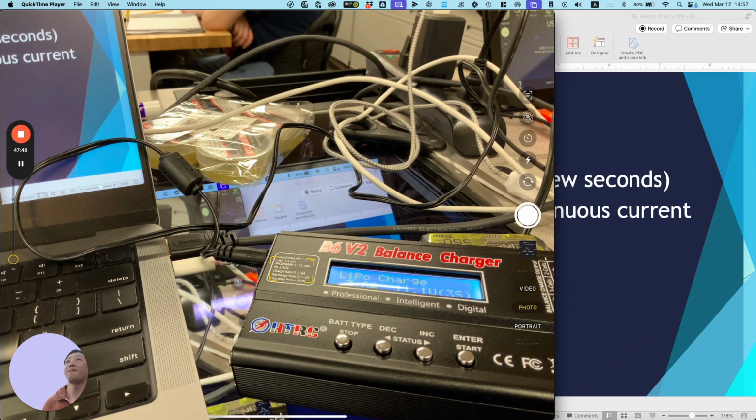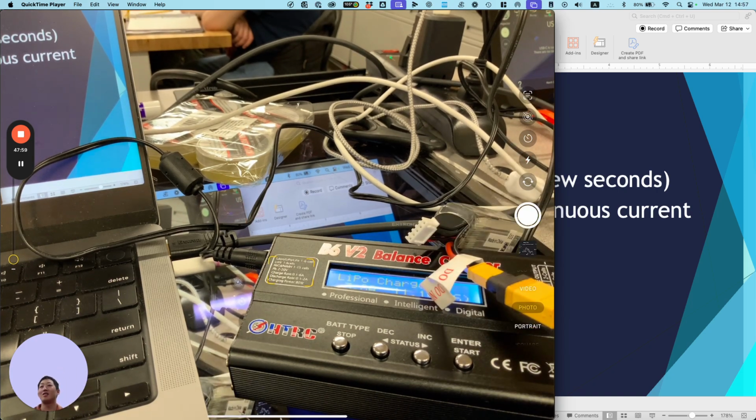When the battery is being used, does it use balance? No, it does not. When you're using the drone battery, it just pulls from it normally. So sometimes later, when you plug it into a reader, it might show an imbalance. Generally, that's an indication that your battery is starting to age, because the internal resistance is building up, and the cells are not going to build up at the same rate.